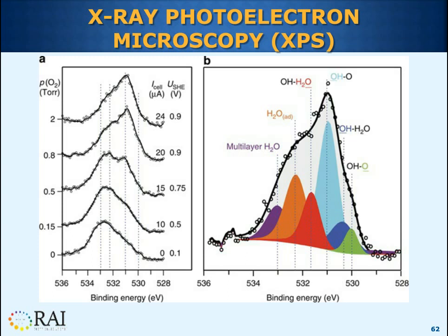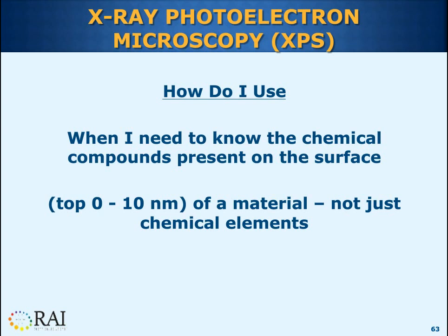So I use XPS when I need to know the chemical compounds that are present on the surface at the top 10 nanometers of the material. And it tells me the compounds, not just the chemical elements. So obviously, XPS is an extremely surface-sensitive technique.